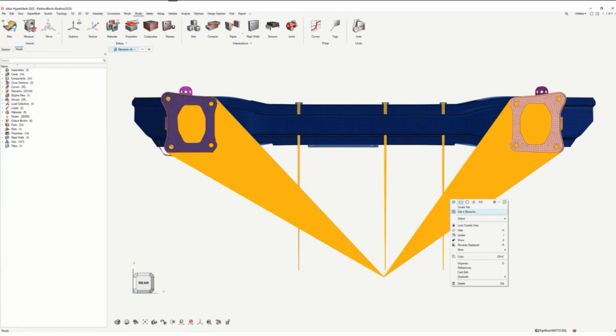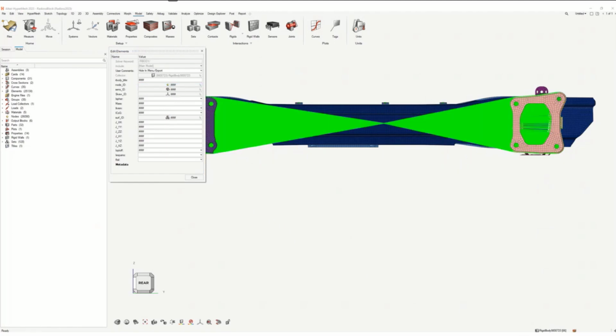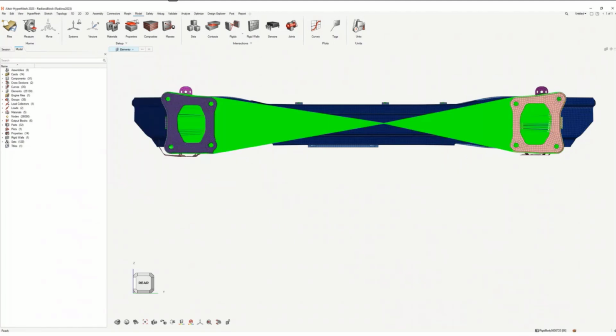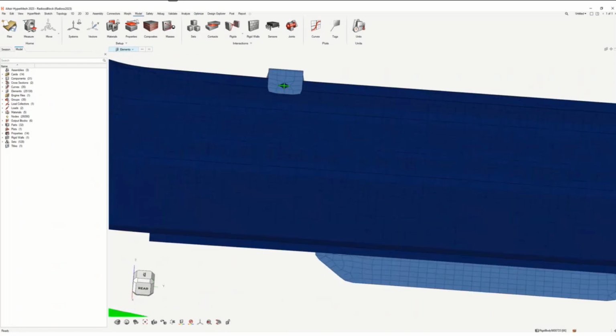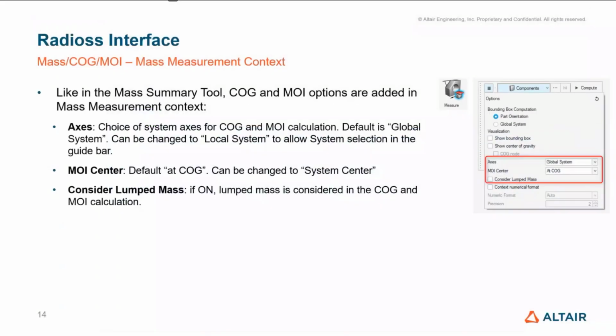So basically here you have rigid bodies with the independent nodes at a certain position. You want to reposition them at the geometrical center of the dependent nodes, and it is done in one shot, and also working, as you have seen, for multiple selections in one shot.